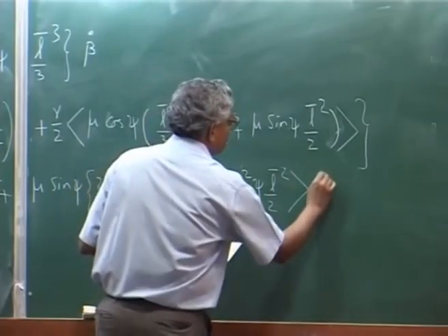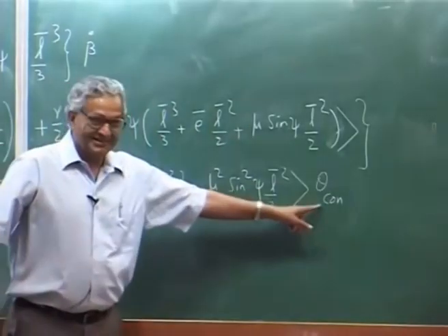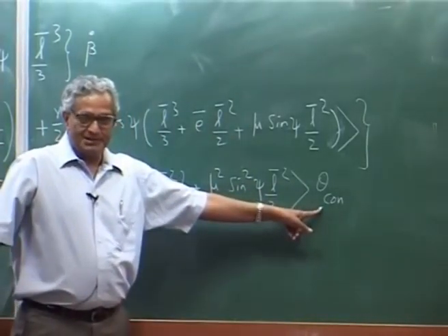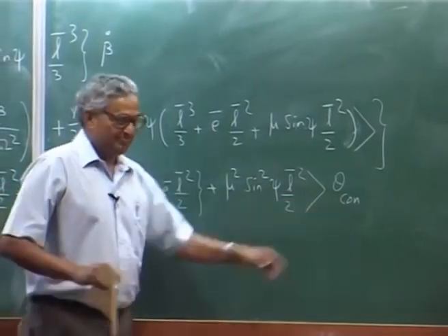This is into theta control input, that is theta pitch input, what the pilot gives, theta naught plus theta 1 c cosine psi plus theta 1 s sin psi, that is this term.